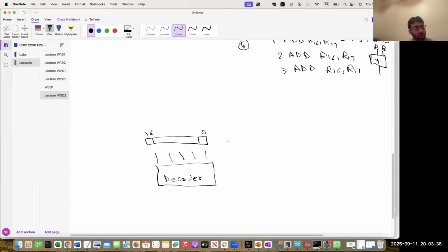As compared to this, suppose we have a situation where, let's say, 10% of instructions are one byte in size, having 0 to 7 bits, and 25% are 2 bytes, another 25% are 4 bytes, and the next, let's say, I'm simply making an example, are 8 bytes. Then the decoder has a problem in all the cases.